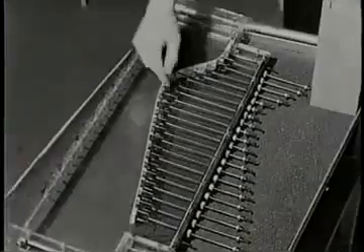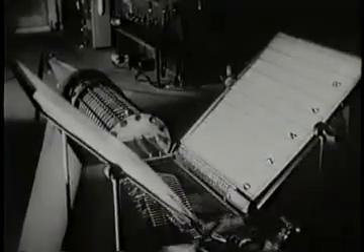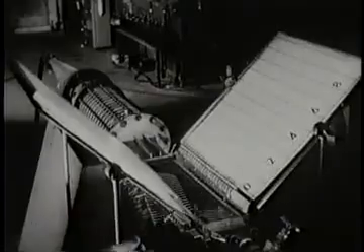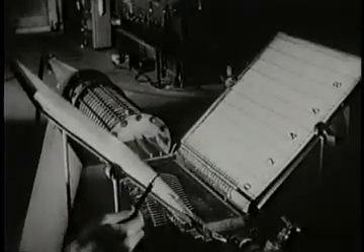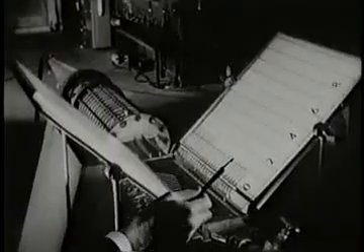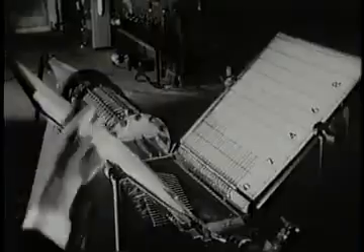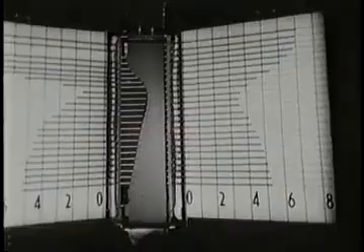Here it is set up for test. These are inclined manometer bores to show the pressure distributions on the two walls. We will observe the lengths of the water columns looking down from a position directly above. Now the flow is steady. We will look first at the pressure distribution on the straight wall.